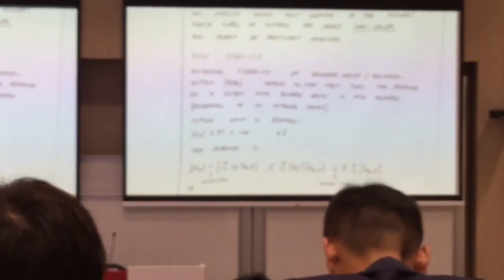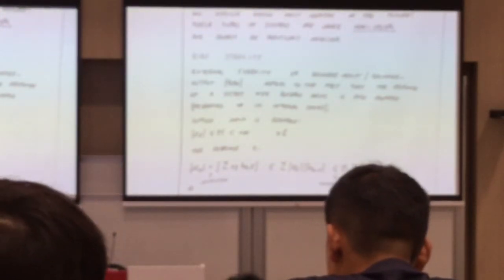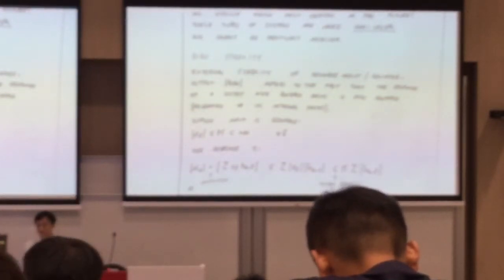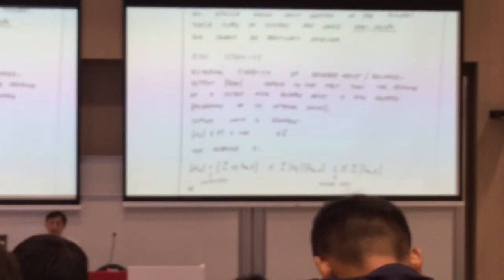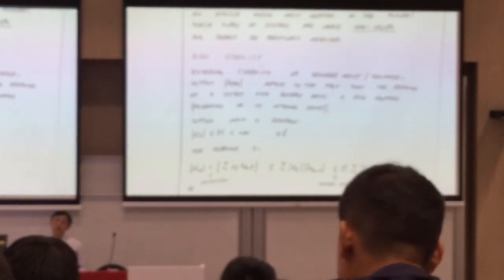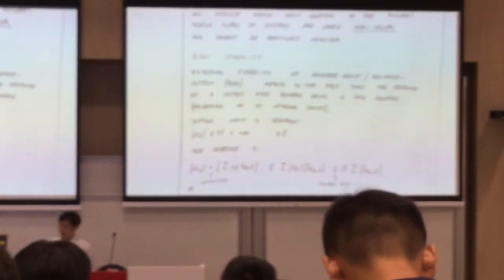So if we do the impulse response, the unit impulse response or the pulse response, we can check the BIBO stability. The BIBO stability means if your input is bounded, as long as your input is bounded, your output must be bounded. Bounded means you have a boundary, a maximum value. You are always less than a certain finite value.